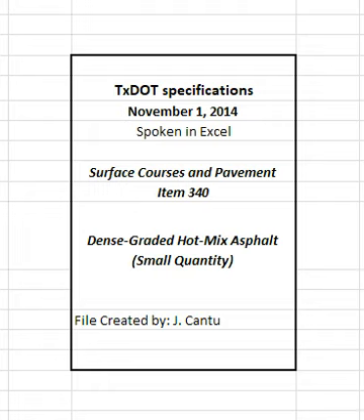Calculate the daily yield and cumulative yield for the specified lift and provide to the engineer at the end of paving operations for each day unless otherwise directed. The engineer may suspend production if the contractor fails to produce and provide haul tickets and yield calculations by the end of paving operations for each day. Prepare the surface by removing raised pavement markers and objectionable materials such as moisture, dirt, sand, leaves, and other loose impediments from the surface before placing mixture. Remove vegetation from pavement edges.